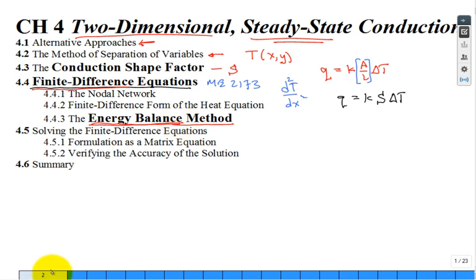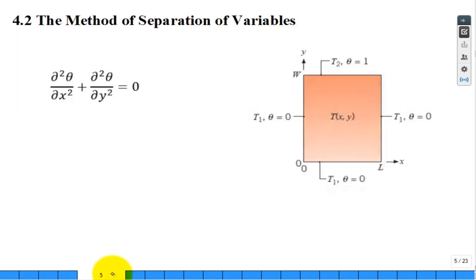Let's jump into it. In 2D, a coordinate system: x goes from 0 to L, and y goes from 0 to W. That's our box, 2D. And somehow we're looking to solve for the temperature at every location in that box. The simplest type of boundary condition is that the temperature on this face is given.